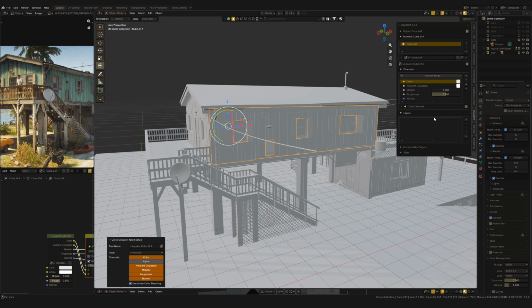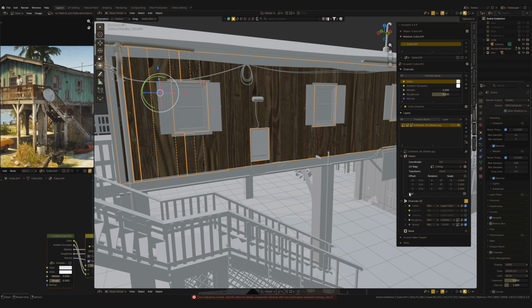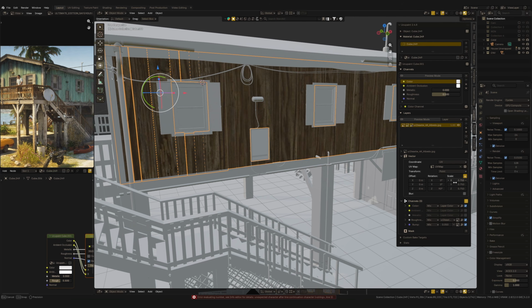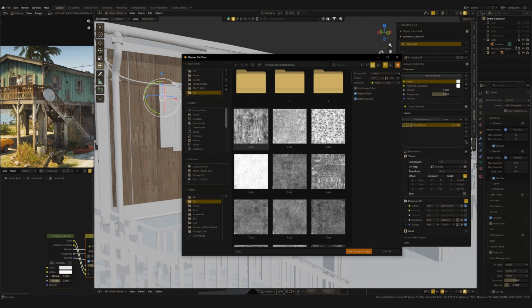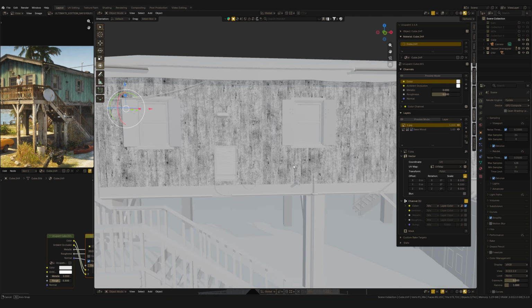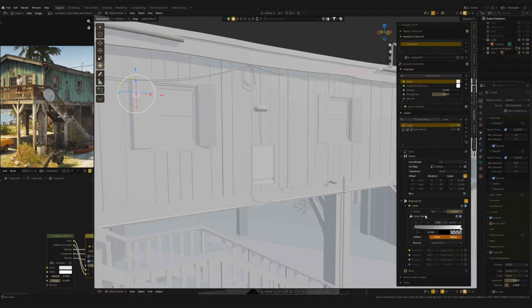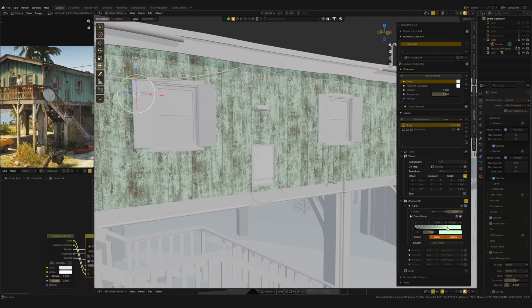It adds a full layered system to Blender, so I can literally build every layer for a complex material and blend them just by painting masks. The base layer for this material is a wood texture. Then comes the paint layer, but instead of just dropping in a solid color, I used a dirt texture instead. It's a black-and-white texture originally, so to give it a color, I use the color ramp modifier in Ucupaint.